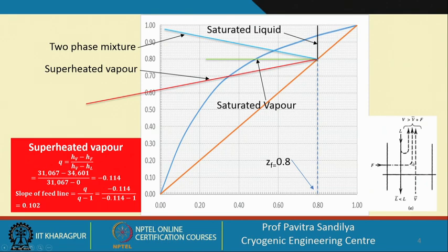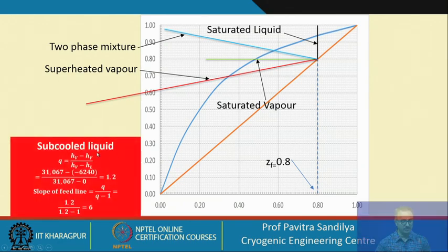So when the superheated vapor enters the column, some of the liquid gets re-vaporized and moves up, and it also adds to the vapor flow rate, so the vapor flow rate in the rectifying section becomes more than the summation of the vapor flow rate from the stripping section and the feed flow rate, and this additional vapor flow rate is coming from the liquid in the enriching section. And now we find that the stripping section has a liquid flow rate which is less than that in the enriching section.